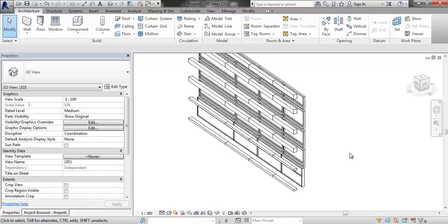That louver extrusion is going to be based on a sweep condition, not like the extrusion, but we're going to sweep a path, right? And by sweeping the path, I'm allowed to load in a profile that has conditions. So this profile is a profile family. Okay? And then from that profile family, I'm going to path in parameters to my generic model. And that's where all this will live.